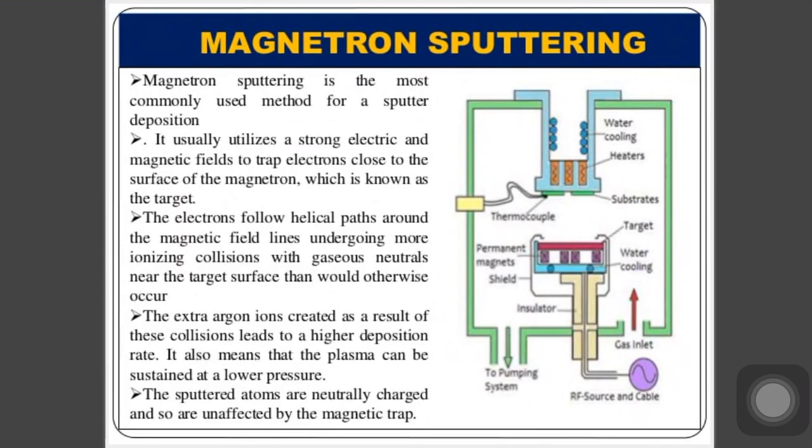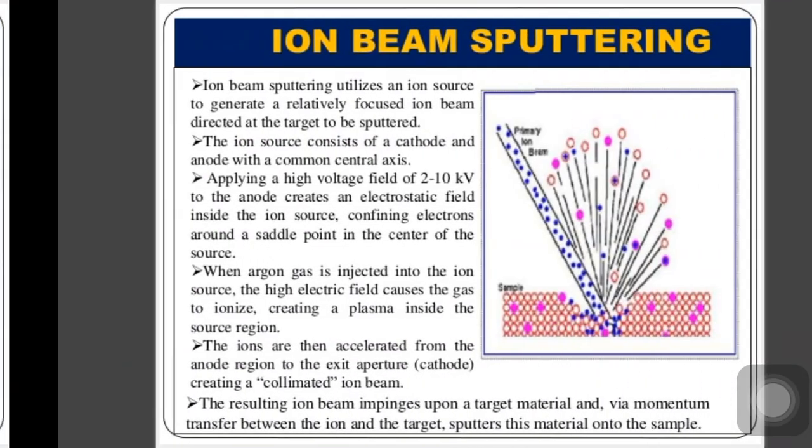This interacts with the substrate materials and the target materials, and due to the electric and magnetic field, the gaseous atoms are ionized, and it is a reactive mechanism which takes place in this closed vacuum chamber. The ionized gas atoms are focused on the targets, and it will change the substrate surface modification properties. So this is the whole process of the magnetron sputtering process.